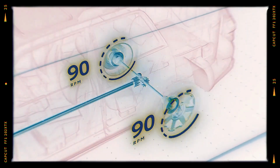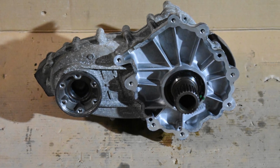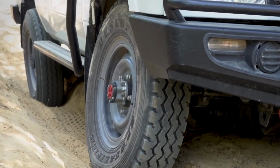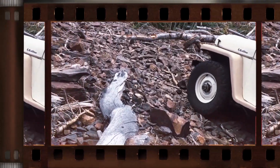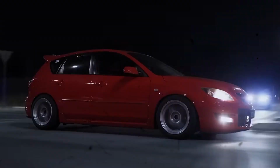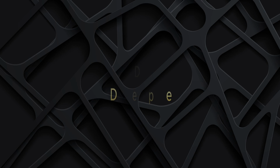At first glance, this task might seem suitable for a regular gear reducer, but in practice, a simple reducer is ineffective when the driving wheels experience uneven loads. For example, if one wheel encounters an obstacle while the other moves on a smooth surface, the transmission requires a specialized mechanism that adjusts torque distribution based on road conditions. That mechanism is the differential.